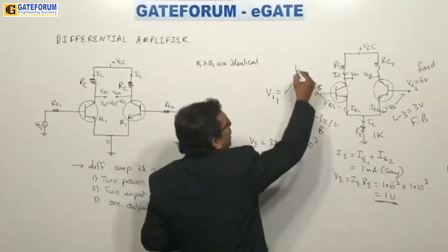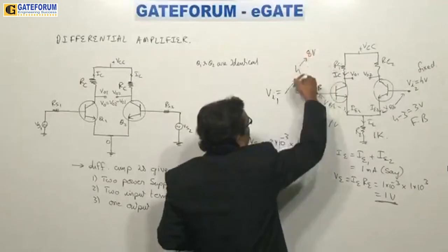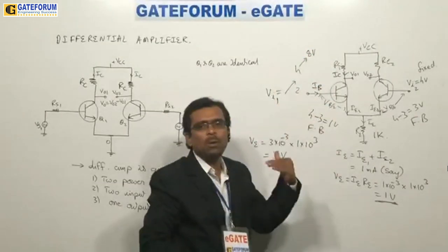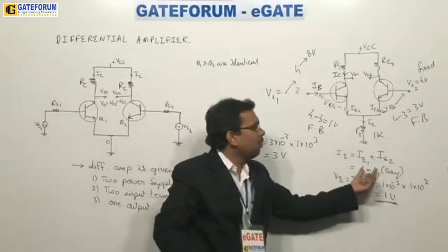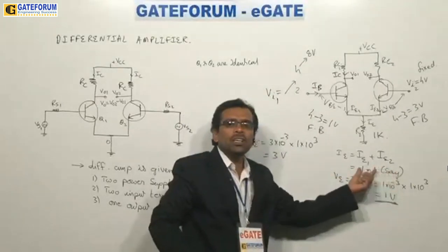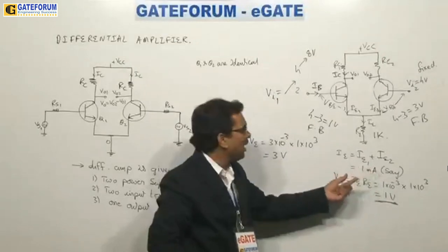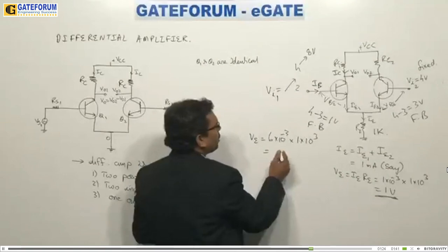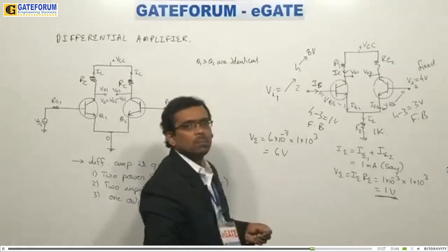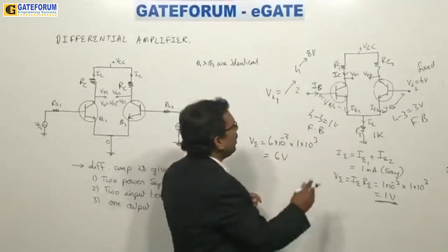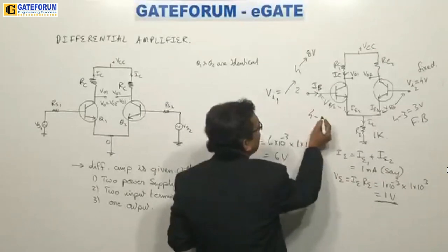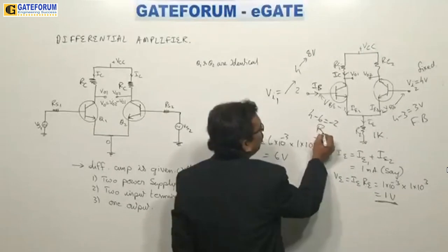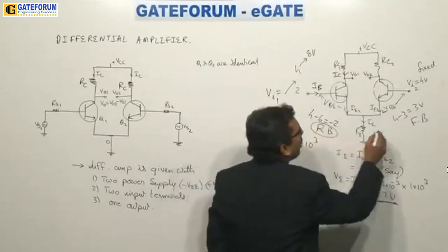Now if this voltage is further increased from 4 to 8 volts, once again current increases and becomes say 6 milliamperes. Sum of IE1 plus IE2 is 6 milliamperes. If it is 6 milliamperes, then 6 into 1, you can see here, now it is 6 volts. At this situation, 6 volts gives minus 2. Now this is reverse biased.